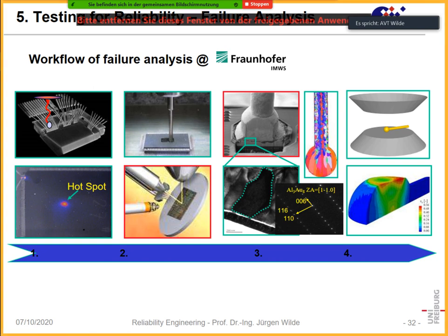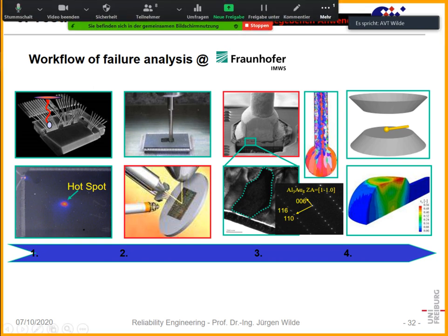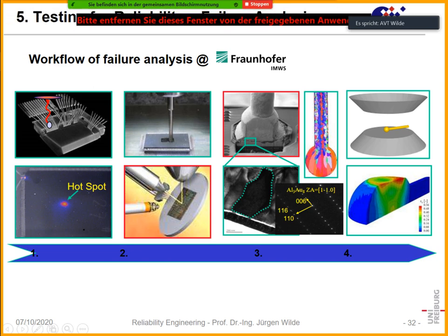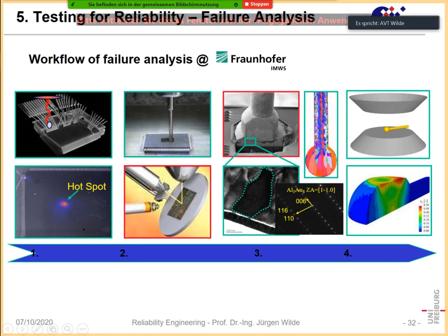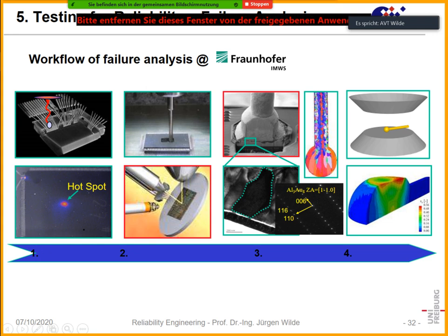Okay, so let's proceed how it would work. For instance, we have a chip which has a hotspot, and that hotspot sometimes can be seen through the molding compound with so-called lock-in thermography. In that method, the device is heated and cooled with a certain relatively low frequency, and in that way, by lock-in technique, a hotspot can be visible, which would hardly be seen otherwise, because it's maybe only a Kelvin or so hotter here.